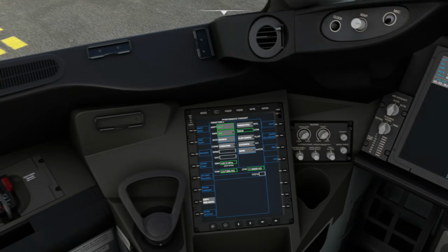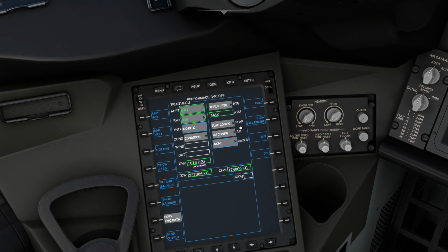But there is a reason for that, and it's, like I say, all those advantages, because we can actually derate our engines more than most other airliners. As a result, using the most runway is preferable for the 787. We don't tend to like to use intersections because they mean more flaps, which means we have to use more thrust, and it's not where the airplane's designed to be.